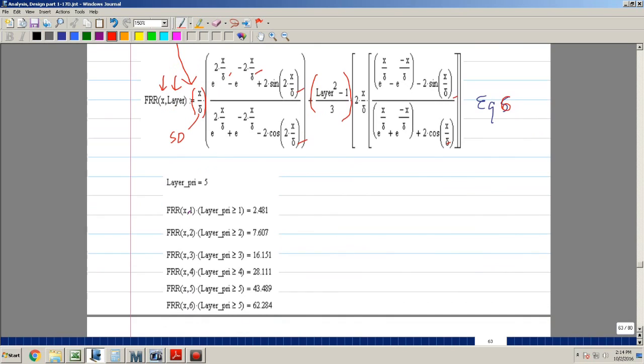And depending on the number of layers that you're going to be using, you get n types of coefficients. What do I mean by that? Let's see if I can explain that a little bit. The main goal is to use one layer per winding, if possible. Why? It reduces these coefficients. In other words, if you have one layer, you can get all your windings in there, then you only need one coefficient, which is 2.48.